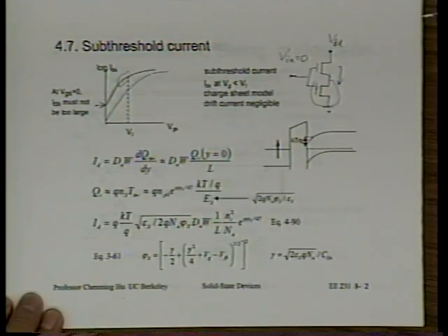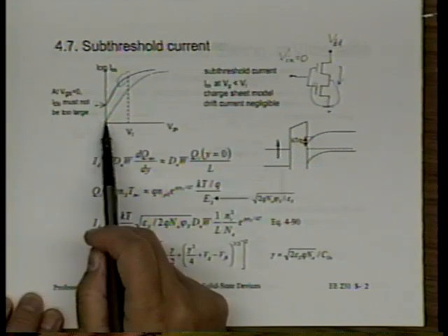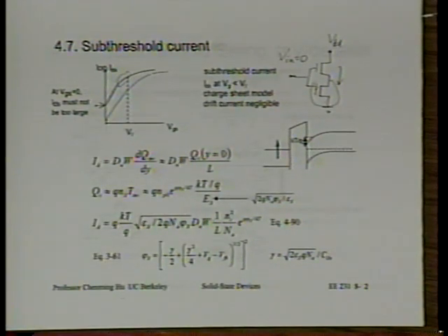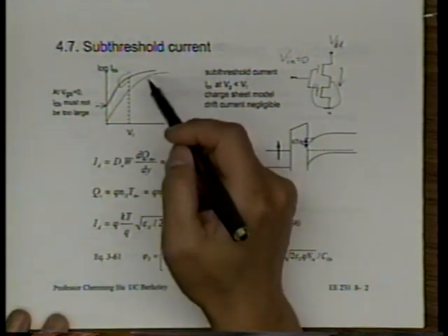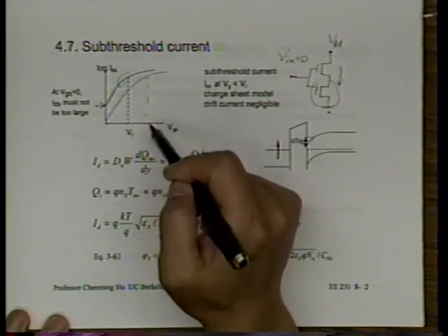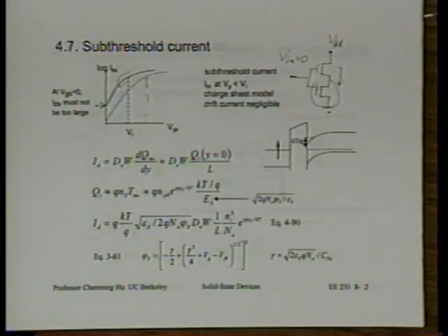It will look like that. Then the leakage current becomes much smaller compared to the original curve. Do you see that? But when we increase VT, if you remember the expression for ID sat being proportional to VG minus VT, or VG minus VT to the second power, then a larger VT will reduce ID sat. And reduced ID sat will make the circuit slower.